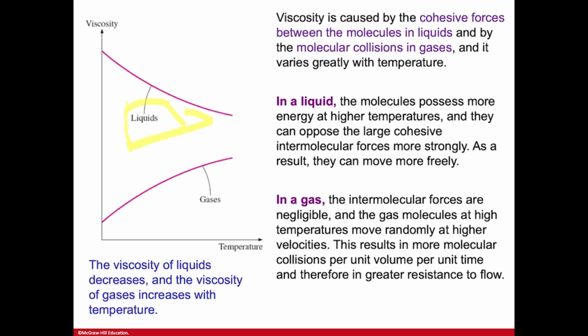But this is not the case for gases, and this is something that you need to be aware of. In gases, because the interatomic forces are weak, by increasing temperature you're increasing the kinetic energy, so the molecules start bombarding against each other more, which actually increases the viscosity. So in the case of gases, the viscosity actually increases with temperature. So this distinction you need to be aware of, right?